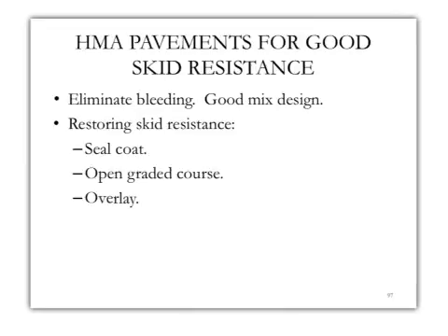So the question here is, okay, how can we restore skid resistance? We know how to measure it. We know that there are several aspects to it in terms of micro and macro textures. Assume now I have a problem, how can I restore it? One option is to use a seal coat as an improvement for the pavement surface, or I can use open graded friction course, or if the skid resistance problem has high extent and high severity on longer sections, then I have to go to the third option, which is the most expensive here, but sometimes we have to go to a 2 to 4 inch overlay to restore the skid resistance of the entire surface of the pavement.